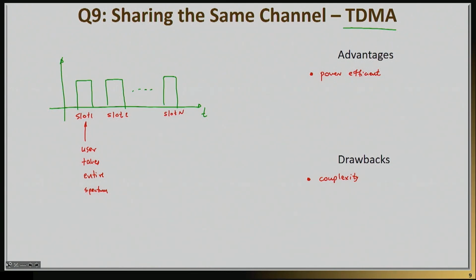So let me give you an example. If we look at GSM, I'm going to draw roughly here what happens. In a GSM system, you have 25 megahertz of spectrum that you can use for all of your users. What we do there is chop this into segments of 200 kilohertz. So these are your channels, if you will.